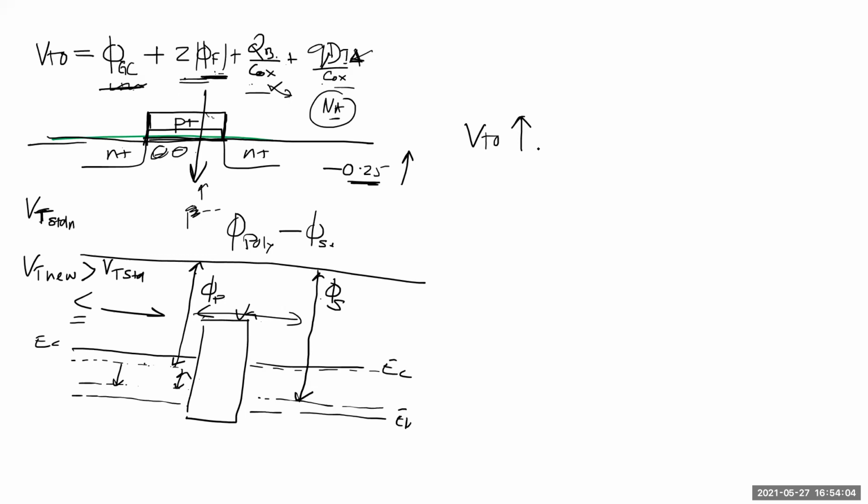Okay, look at it this way, maybe this is a good way to explain it to you guys. You remember I said yesterday, the contact potential doesn't matter what you take in the stack, right? If you have some material M1 here and some material MX here, then the contact potential, this phi GC term, phi M1X, is determined by the two end ones. So what if I made this gate doping exactly the same as the substrate doping? Then it'll be 0, right?